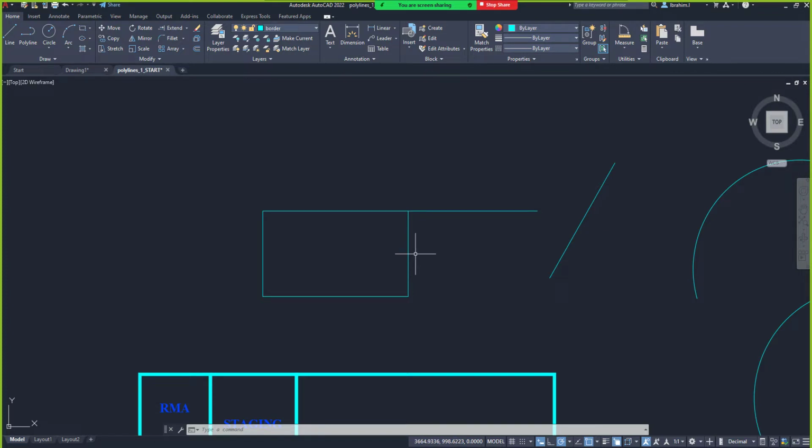Are you with me? I want to start another line command again. I want to start it from this endpoint that is here. By default, immediately it shows that box for me. I don't have to doubt. The line is starting exactly at that endpoint. Are you with me? But now I will go ahead again and turn off my endpoint completely. Can you see that blue color is not showing over it again? Now I've turned it off completely.